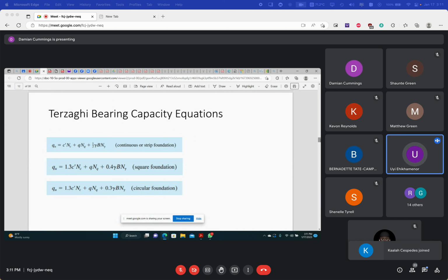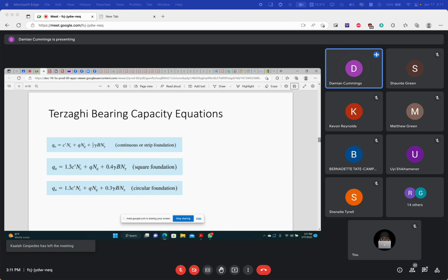So could you repeat that please again? Right. I'm saying that the passive pressure coefficient will give us an indication of what fraction of the vertical load that is applied from our structure actually also acts laterally below the foundation and will result in failure.